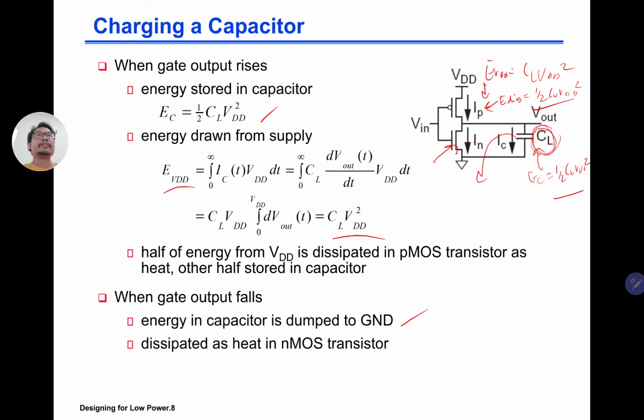in the transistors. If you have 1 billion transistors in a microprocessor, like the Intel processor, and you have heat dissipating from each of the transistors, that's why your device gets hot. And the higher your energy dissipated, the higher CL and VDD, then the higher the heat that's being dissipated.